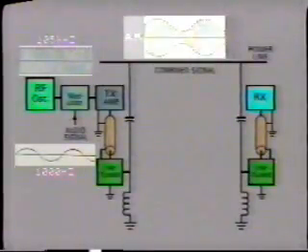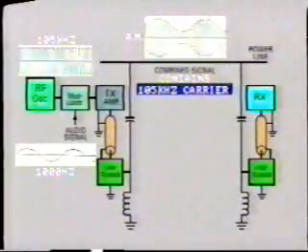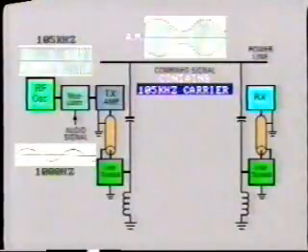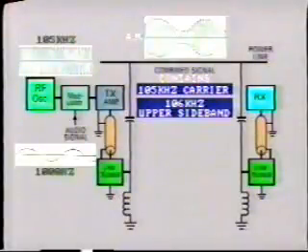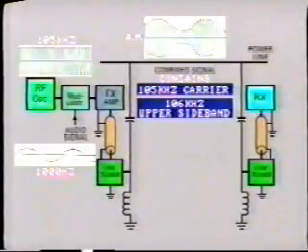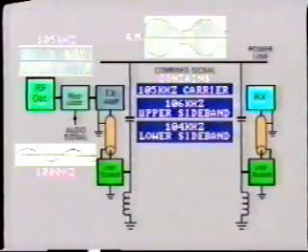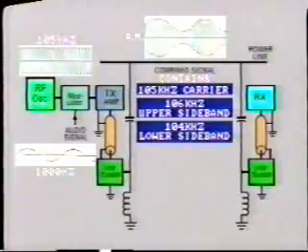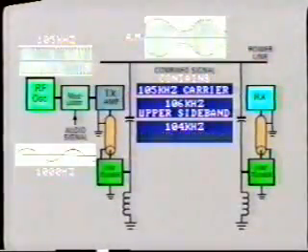When this signal is demodulated and analyzed, there are actually 3 frequencies present at any instant. The 105 kilohertz carrier is one. Another is the 105 kilohertz plus the audio signal frequency, 1 kilohertz in this example. That is 106 kilohertz. This is known as the upper sideband. In addition to this, there is one more signal, that is 105 kilohertz minus the audio equals 104 kilohertz. This is the lower sideband.